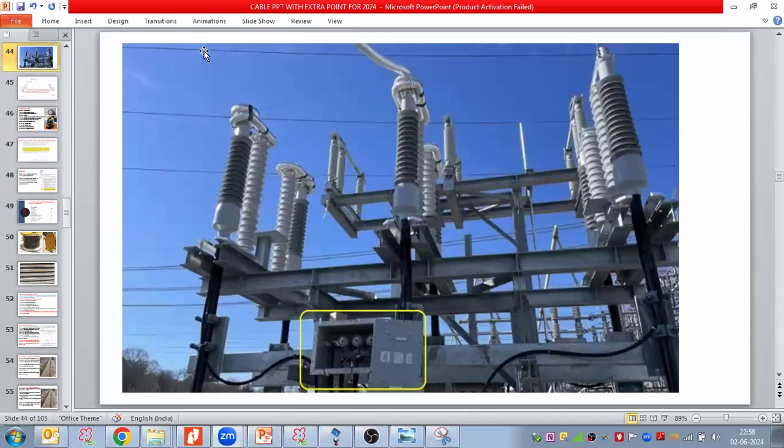Raghav sir, I have some doubt actually. You told me that the cable charging current will be mentioned in the cable specification. There is 1.3 times like that. Is there any limit for the charging current? How can we accept it while reviewing the document? It would be better if we can check through the cable standards, there should be some value about the charging current. I will check, Rajkumar. There might be some value in the specifications as well. That's fine. For reviewing and approving, we should know the limit or something like that.